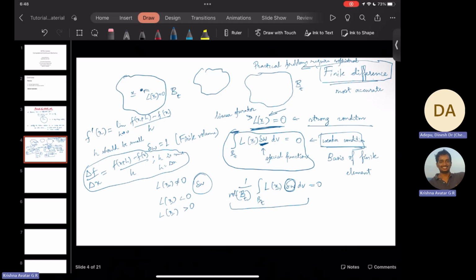Yes, Foam Extend is the only software which uses finite volume to solve structural problems. There are a lot of drawbacks in finite element methods for solid mechanics, which are able to be mitigated by using finite volume even in solid mechanics. One of the problems is large deformation. In large deformation, finite element suffers from a lot of problems in convergence, which is mitigated using finite volume.